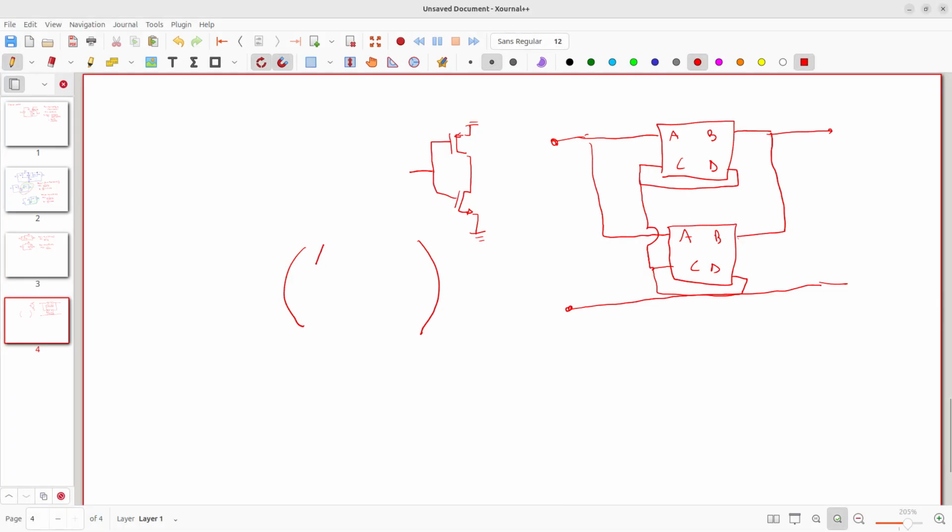The voltage gain is actually the same. The current gain increases by a factor of 2. The transimpedance factor decreases by a factor of 2, and the transadmittance is exactly the same.